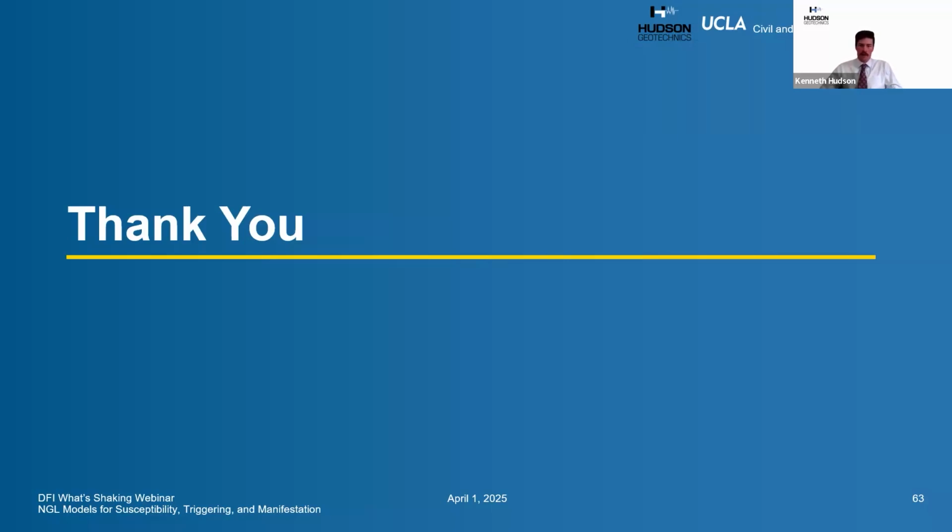It was just volumetric strain at depth. There's no indication at the ground surface that that happened. There was no pore pressure sensor at depth detecting these things. There was no strong motion station that showed a change in frequency content of the ground motion due to liquefaction at depth. There would be no evidence.